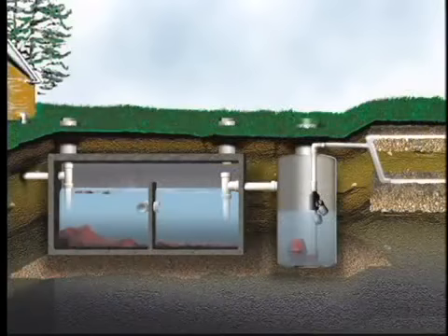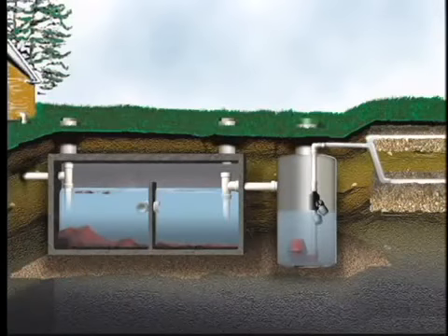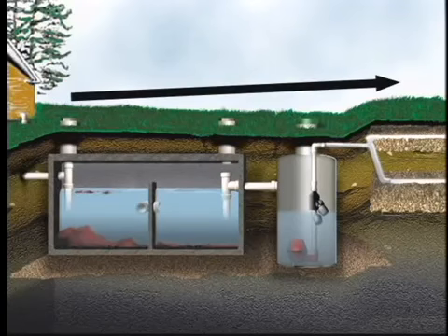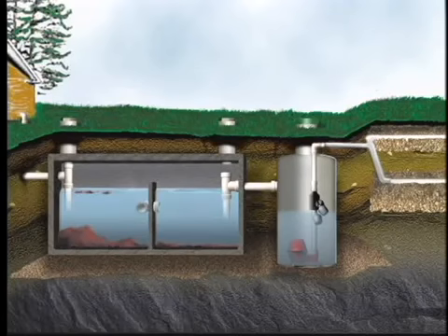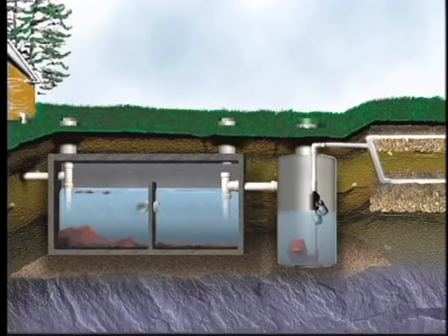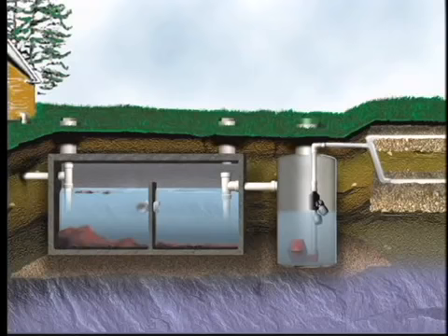This system is generally used to move effluent from a treatment site that sits at a lower elevation than the application site and in soils with high clay contents. It is also used in shallow soils where seasonal high groundwater and bedrock occur between 3 to 4 feet below the soil surface.